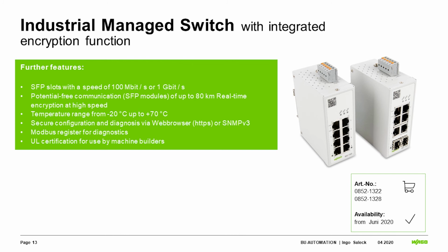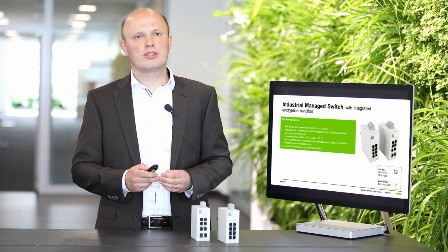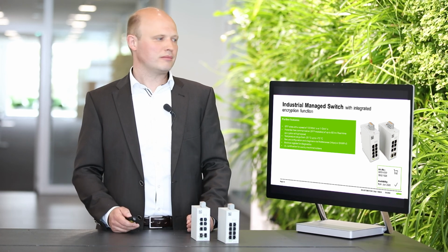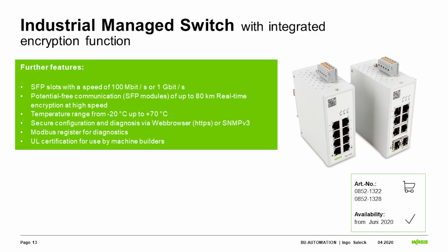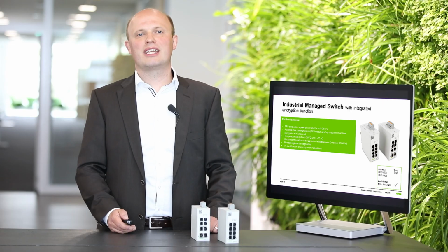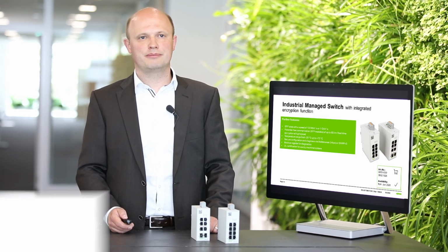Then we have a big temperature range from -20 to +70 degrees. We have integrated configuration and diagnostics, for example, for web browsers in HTTPS, or you can use SNMP v3 with a higher security level. You can use Modbus as well, for example, for diagnostics to get information from the network. And we have the UL certificate, especially for use in America and Canada.